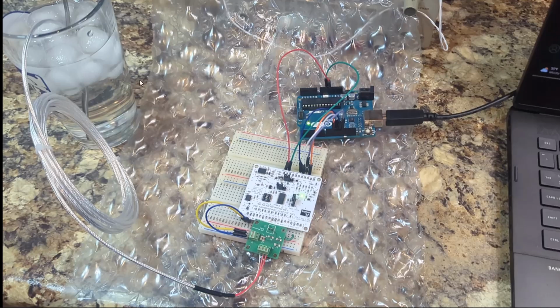And you might see this glass of ice water over here. So I have this sensor as well as a reference sensor that's connected to my DMM in this ice water. And the reason I went with this ice water is because I found that me breathing on the setup or the exhaust from my computer would change the sensor values because these sensors are set up to be very sensitive. And because the sensors are a little bit of different construction, one would heat up or cool down faster than the other. So what I found is if I put it in liquid, it works better for this demo because I get a nice stable reading.